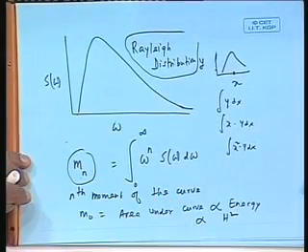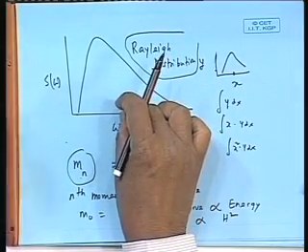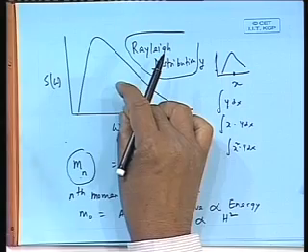Now, if you have a Rayleigh distribution graph, it turns out that all the statistical formulas connected to the average wave height, significant wave height, all possible properties become connected to this. If you know the spectrum and its area and the moments under the graph, especially the area, in fact all the heights become proportional to the area.